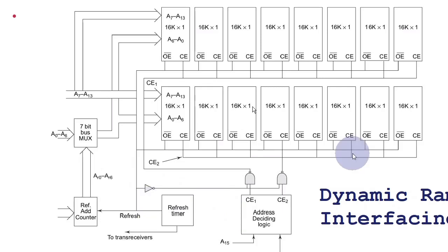And if you want to connect it to the 8086 system, this is the address decoding logic that you are going to use from A14 to A15, whatever is your logic. You are going to connect the address mechanism from here, and there has to be this separate refresh mechanism which will have a counter and a refresh timer to timely refresh them to their original values, right? So that is why this additional mechanism is introduced.